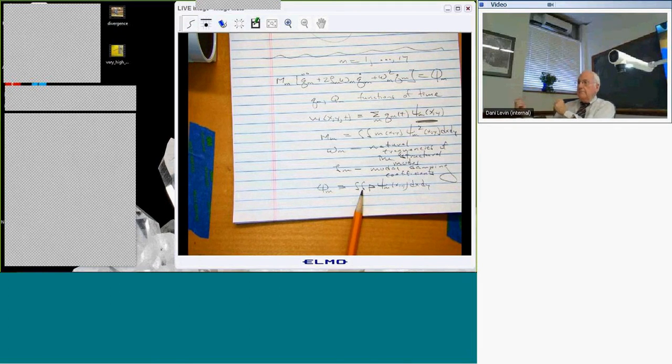But often, for random motions, you only want to do two things. One is you want to know the average value of the time response, and you want to know the fluctuations about that as represented by the root mean square deviation from the mean response. And if that's all you want to know, and often your knowledge of the input is such that that's all you're really justifying knowing, you don't know, that's probably about all you know about the input too.